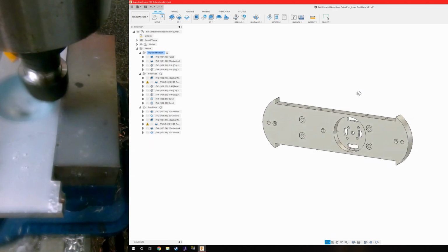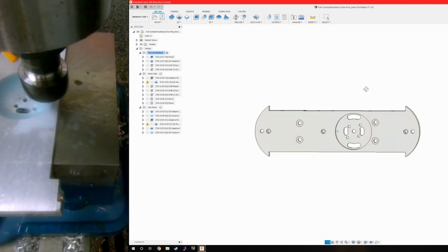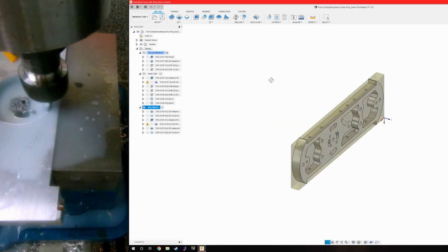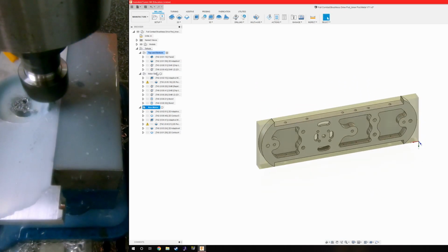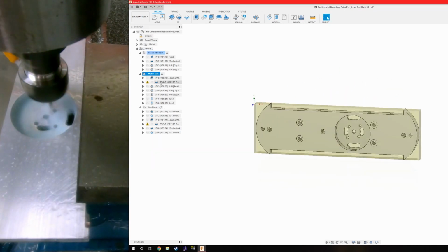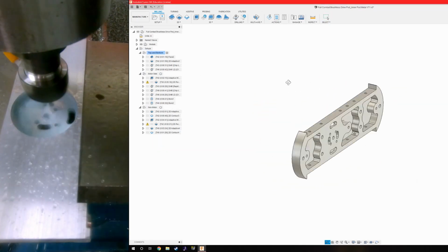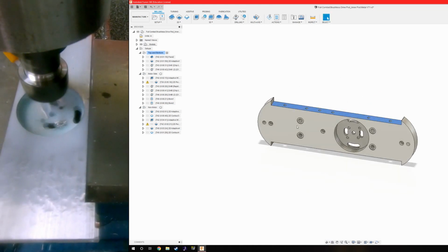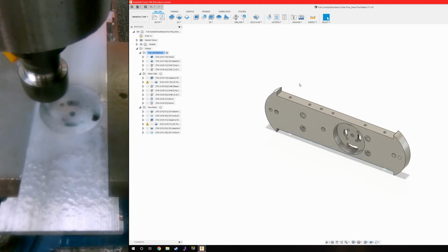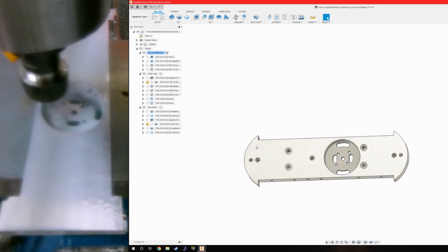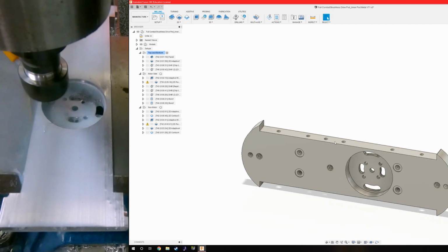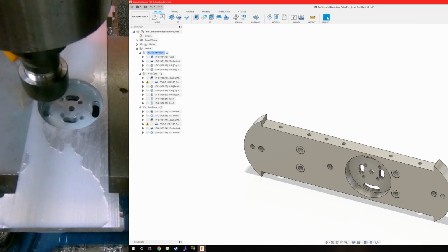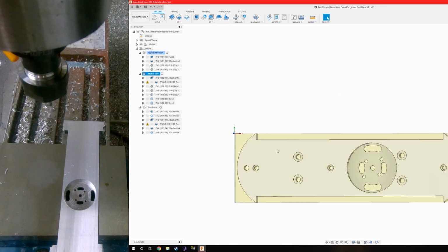But I did have to make sure that I was referencing the correct point for my datum for each of those. So you can see here, I have to flip it the correct way again to make sure the datum ends up in the correct place. And also, because I had milled these faces in, I actually needed to not use the vice corner anymore because I had to offset it back by a 1/4 inch, since the vice surfaces would be gripping here and here instead of at the stock dimensions that are shown this way as being 2.75 inches.